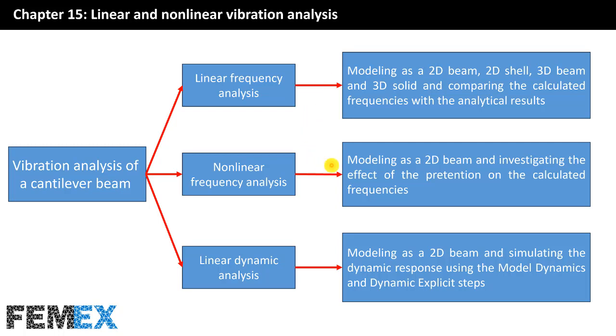In the second procedure, I have modeled the problem as a 2D beam and investigated the effect of the pretension on the calculated frequencies. And finally, for the linear dynamic analysis, I have modeled the problem as a 2D beam and simulated the dynamic response using the modal dynamics and dynamic explicit steps. And finally, I have compared the results.